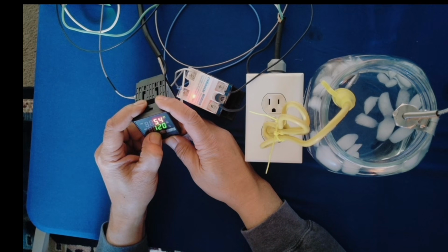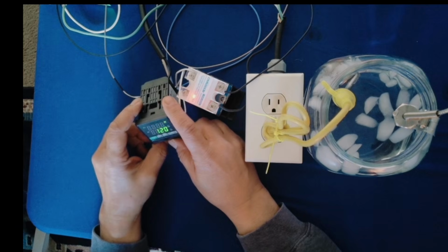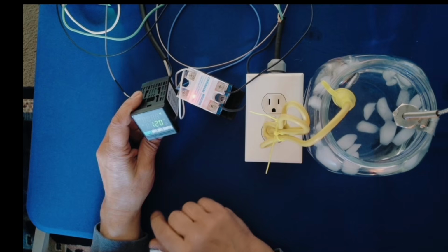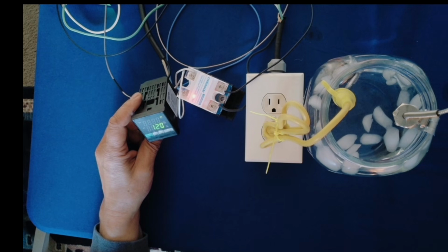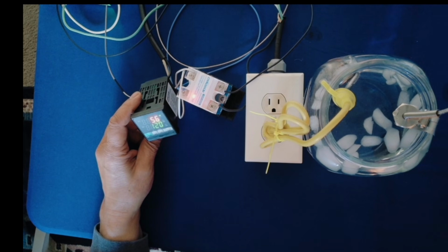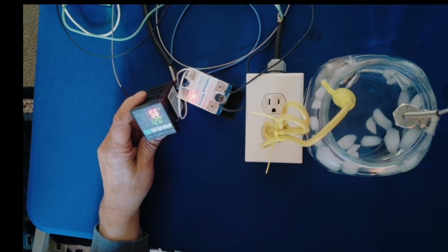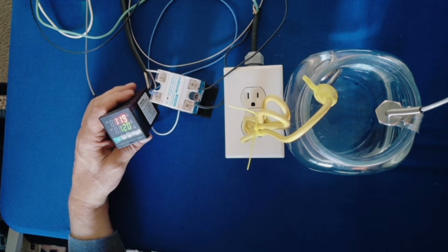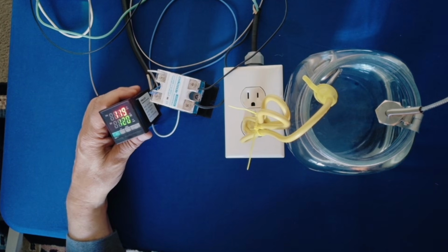Next, we'll enable Auto-Tune. Once Auto-Tune is activated, the temperature display will begin flashing. The controller will then start automatically tuning the PID parameters for the process. When the flashing stops, that means the auto-tune process is complete. Notice that when the process temperature is far from the set point, the relay stays on continuously. As the process variable gets closer to the set point, the relay begins turning on and off. This allows the controller to regulate the heat and maintain the temperature at the set point.